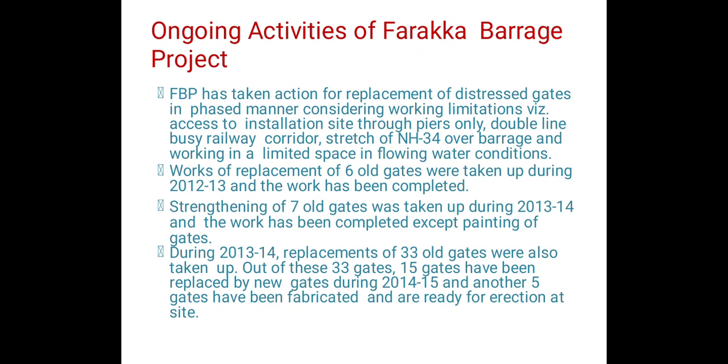Ongoing activities of Farakka Barrage project. FBP has taken action for replacement of distressed gates in a phased manner considering working limitations. For example, access to installation site through piers only, double line busy railway corridor, stretch of NH34 over the barrage, and working in limited space in flowing water conditions.